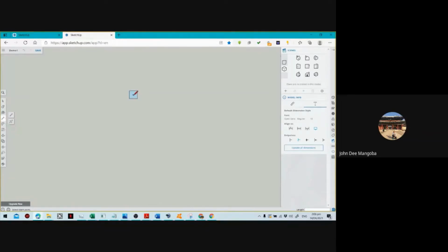It won't show up right away. Oh, the midpoint is available. The midpoint is available. There. So, SketchUp helps us determine where the midpoint is. But in case it's not available for you, what you can do to find where the center of your square is, is by using the corners. You make its diagonals and then you will know where the center is. Okay? Because that will be our basis later. So, since we have the midpoint, we'll just be using the midpoints as our guide to find the center.